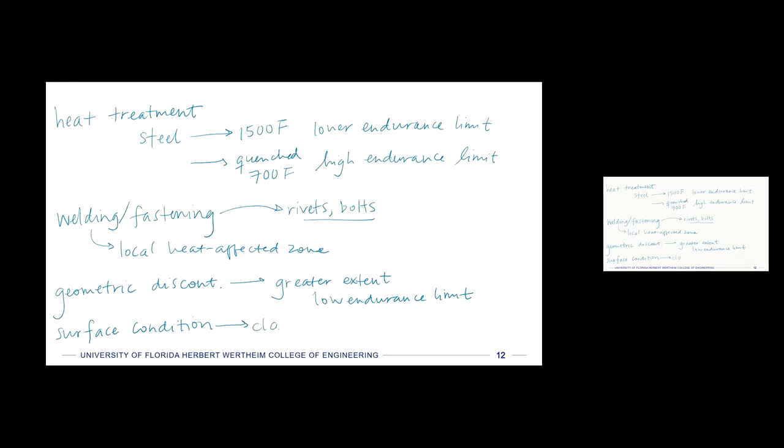So any kind of cladding or other kind of thick coatings and then plating procedures can have a really big change on the endurance limit. Small changes occur for thinner coatings, so like anodized coatings. Right. In that case, the endurance limit is not changed very much. Or if you plate it with something that is a pure metal, such as zinc or cadmium, except cadmium is not as environmentally acceptable.